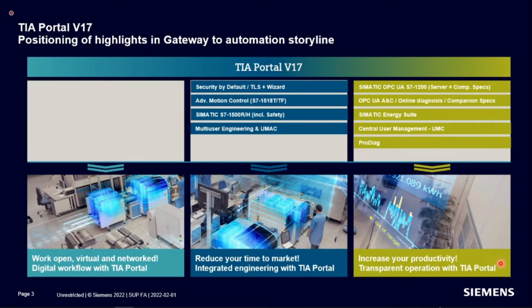And for this exclusive engineering, by default there is no license required. Like in multi-user engineering, a separate license is required, but in case of exclusive engineering, no separate license is required. It is only the project manager or the project server where the TIA Portal project server has to be configured.